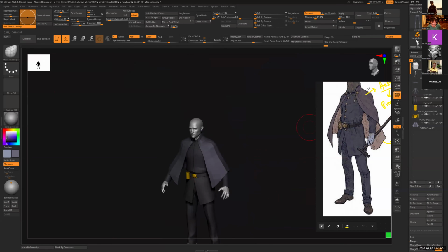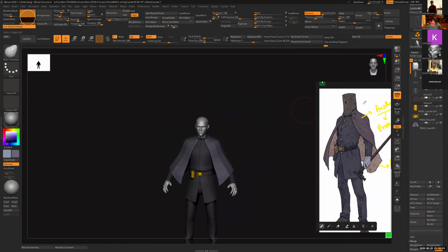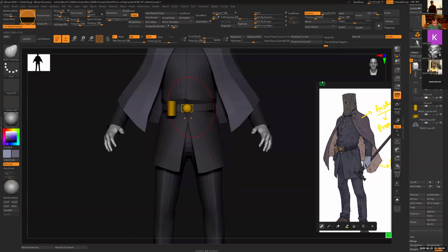Okay, not bad. Let's make the helmet, because that's one big thing that we need to wrap up, so that once the helmet is done, then there are a few more smaller things like buttons. You have to keep the UVs of the same clothes in the same UV island, or mixing. So you look at the textile density. I see that this one type of fabric is taking about 80% of the character. And if I keep it all in one UV sheet, then textile density would be lost. So I would split this into two different sheets so that the textile density is consistent.